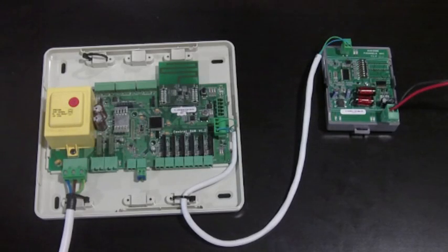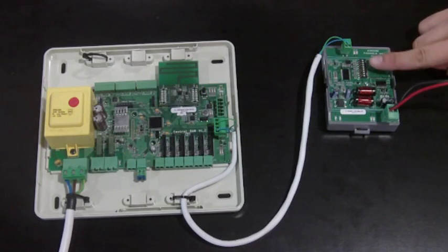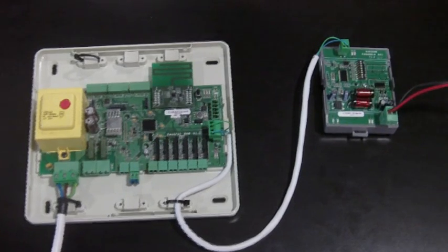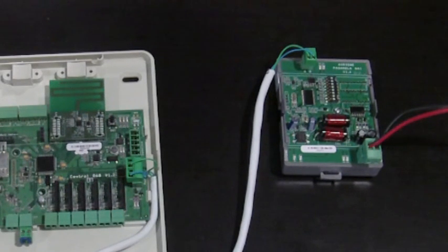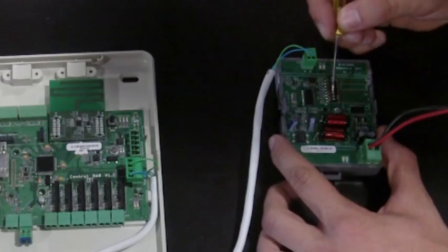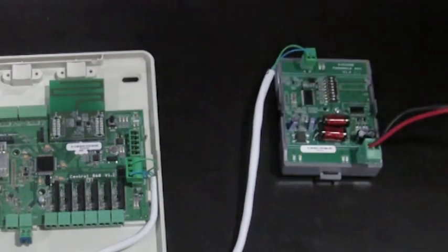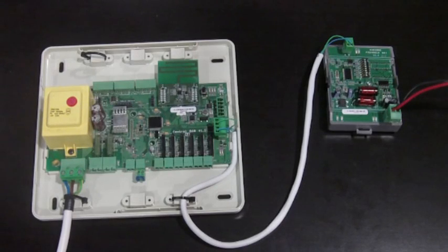Once every connection is accomplished, the microswitch must be configured according to the type of installation, if there is a bypass or not, and the number of indoor unit fan speeds available. This configuration determines the information transmitted to the indoor unit and remote controller in order to optimize the installation performance. Once connections and microswitch configuration are accomplished, power the zoning system and the AC unit simultaneously.